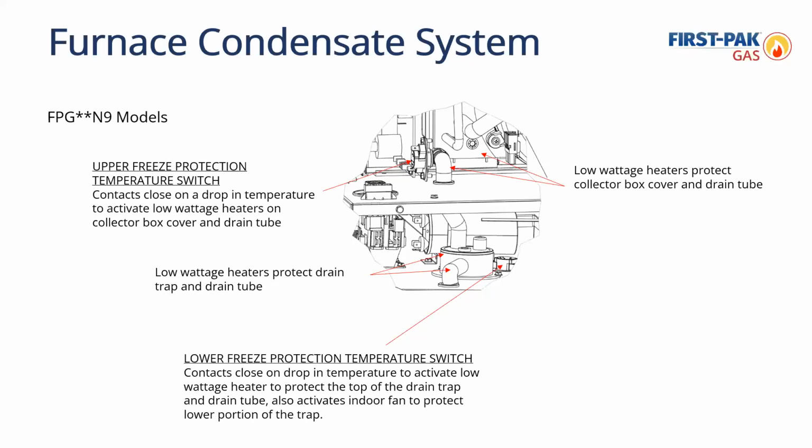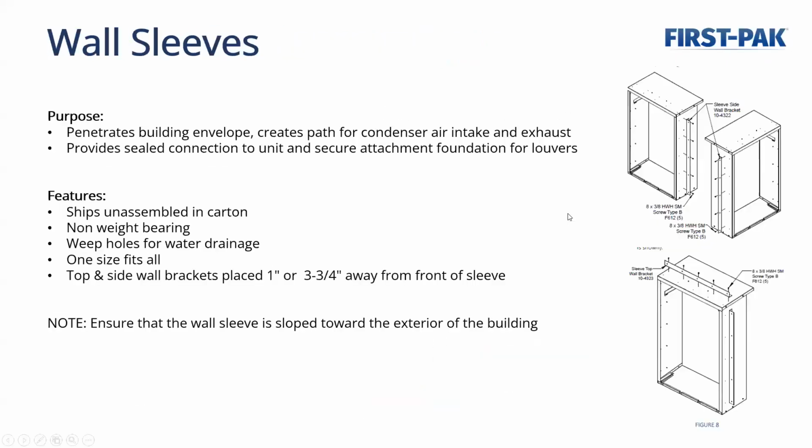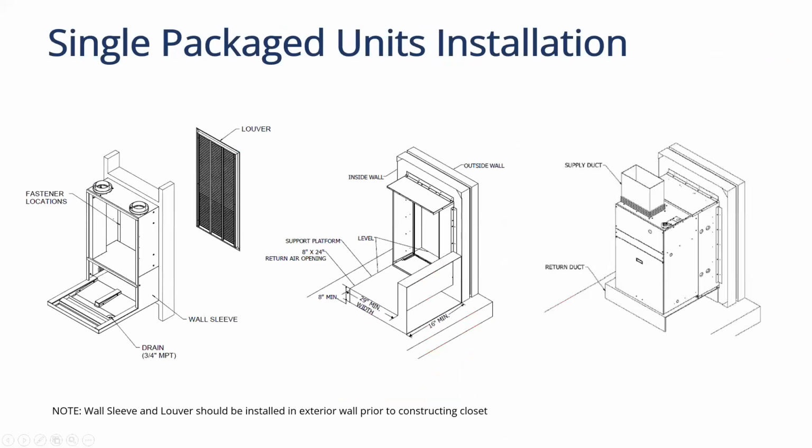Yeah, so basically during the installation process, the wall sleeve will need to be caulked and sealed between the wall sleeve and the wall opening. And then depending on which unit, let me go back real quick to this one here. On the Eco Series, on the unit on the far left, that louver actually is flush into the wall sleeve and attaches and then is pushed through. So there's no additional sealing needing to be done around the louver itself. It would just be around the wall sleeve.